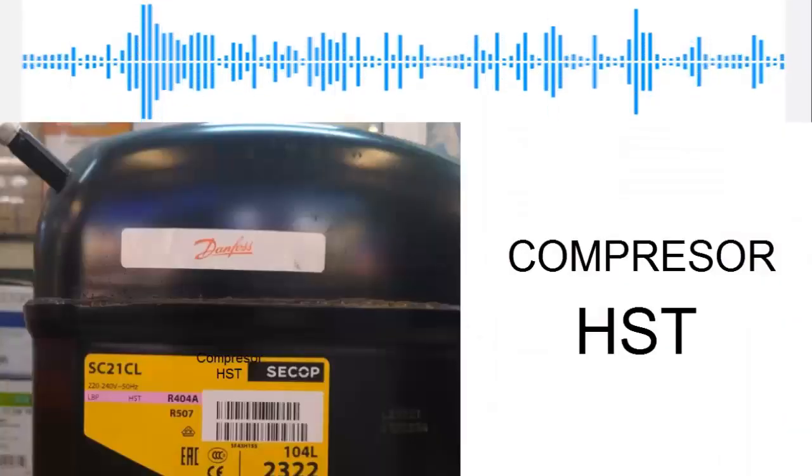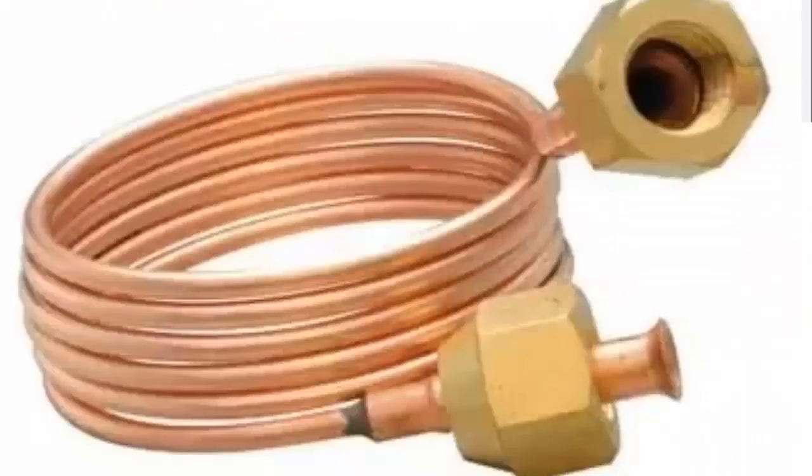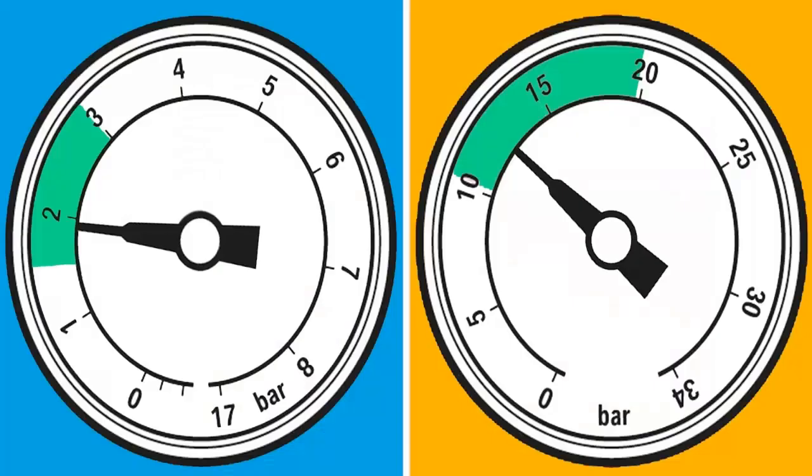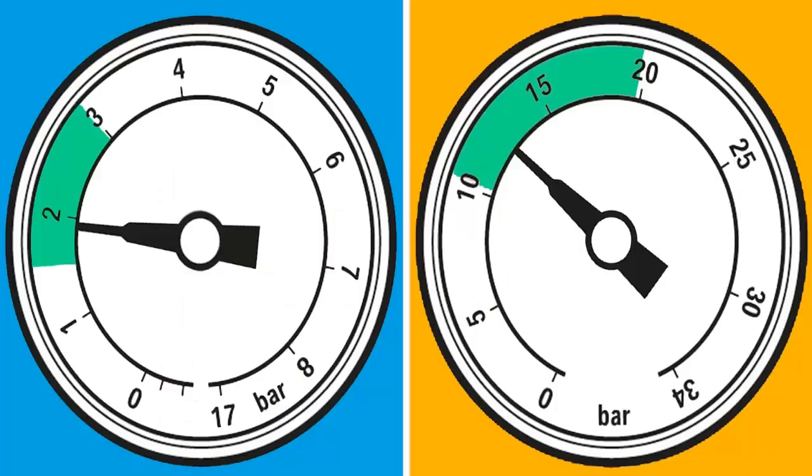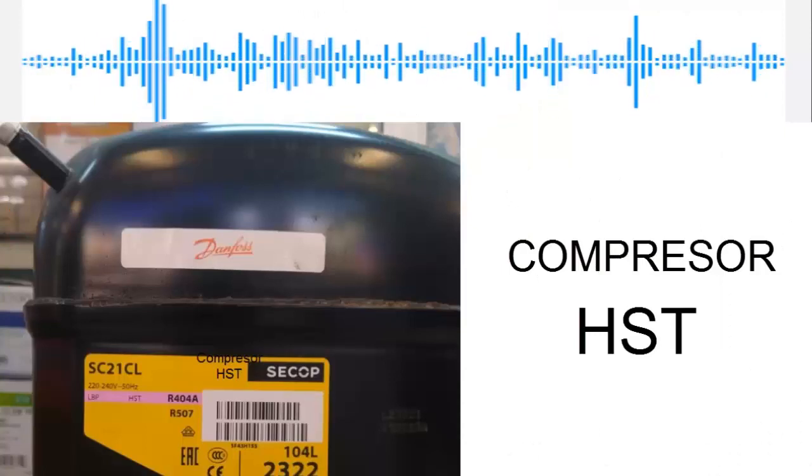Remember that systems with a capillary tube are devices whose balance or pressure values between low and high pressures equilibrate quickly once the equipment is turned off. On the other hand, systems using a thermostatic expansion valve take much more time to balance or equalize their low and high pressures after being turned off. Therefore, during the compressor's next startup, starting the motor becomes more challenging.